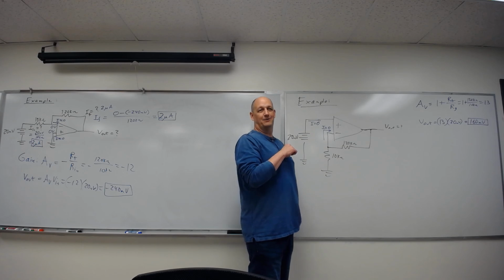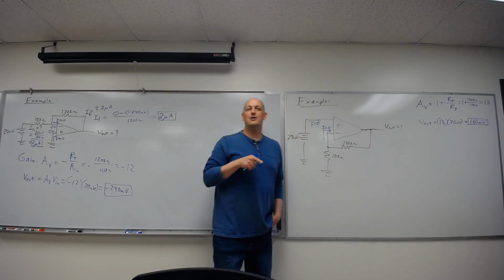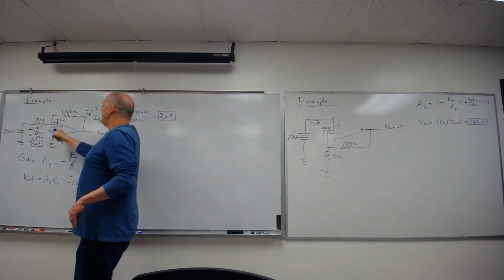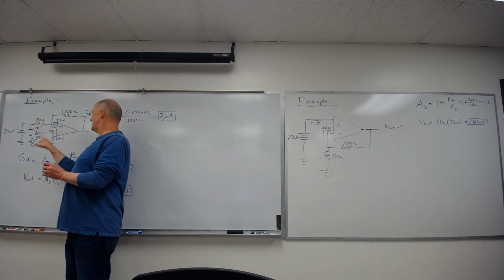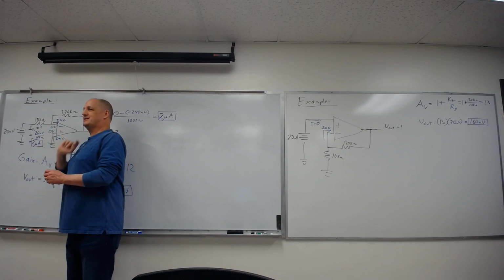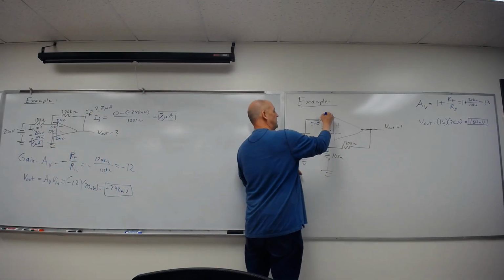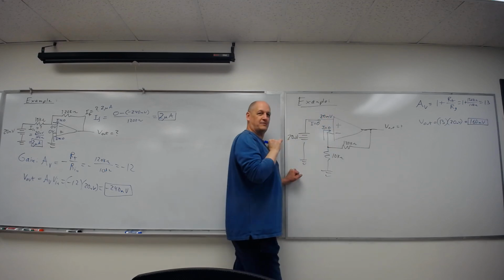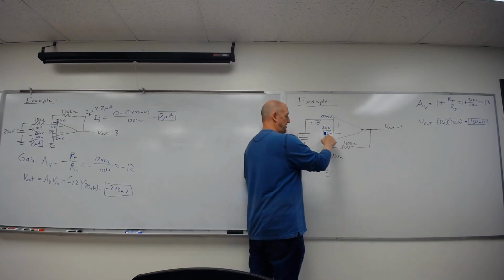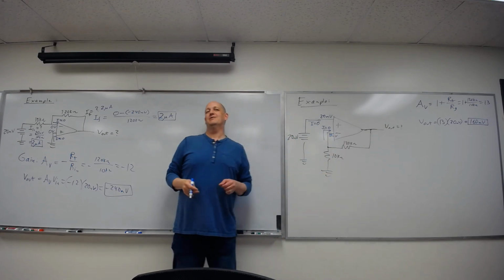No! My two inputs, okay, don't let this confuse you. Over here, they're both 0 because this one is tied to ground, which is 0, which means that's 0. Over here, this one is 20 millivolts because we're tied directly to a 20 millivolt source. Therefore, this one is also 20 millivolts. I didn't say that one of them is 0. I said they're identical.